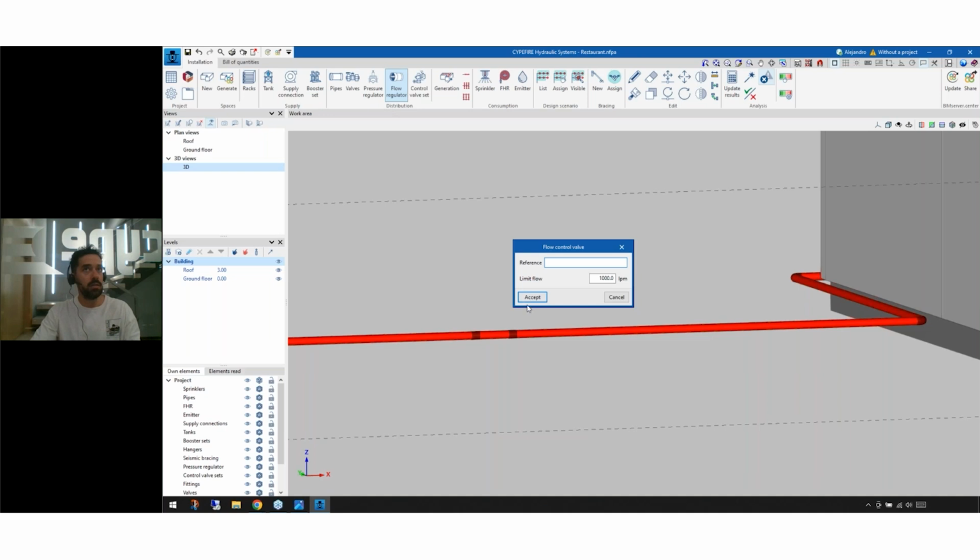So the flow regulator works really similar to the pressure regulation, but in this case, I'm introducing a limit for the flow. We work with EPANET to run this hydraulic analysis here. There is a difference between this flow control valve and the pressure regulation valve: you cannot have more flow than the one you have in the pipe.